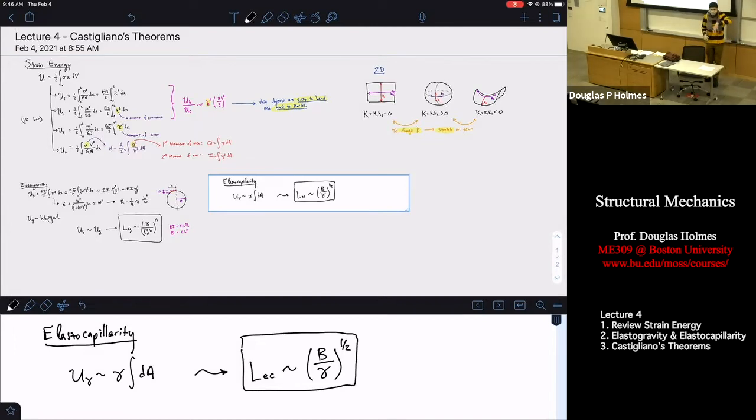If you're using fibers to pull up a fluid with capillary action, this length will tell you if those fibers are too soft, the fluid is actually going to cause them to coalesce, and it's incredibly hard to get those fibers to separate again. So by just comparing two energies, these things give you an idea of at what length scale those things will be comparable. Above that length scale, like the gravity length, gravity wins, your sheet bends. Below that length scale, bending rigidity wins, your sheet stays flat. So there's a lot we can do conceptually just by looking at these energetic scalings.